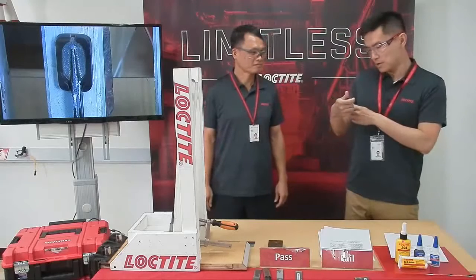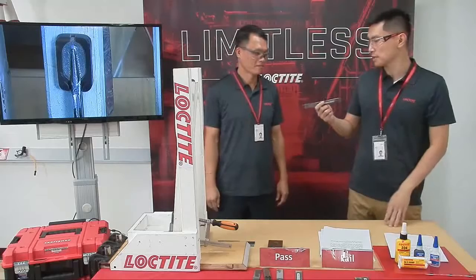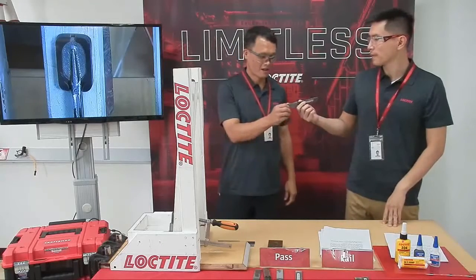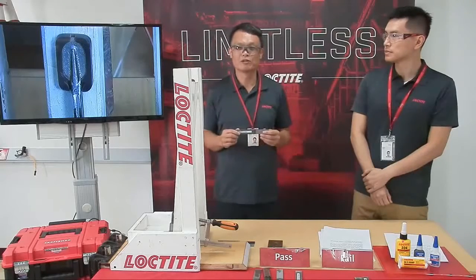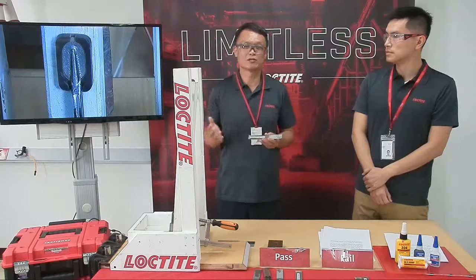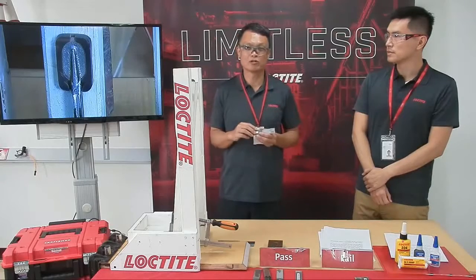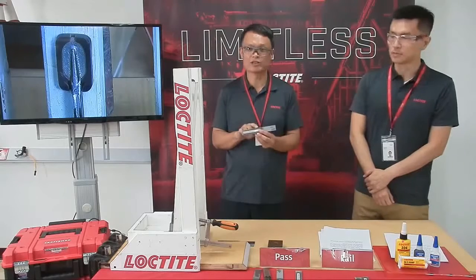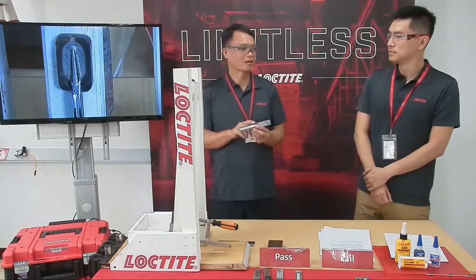So when you say structural acrylic, I know what acrylic is. Then what is the difference between these two? Because acrylic resin is very brittle, it's not the right candidate for structural bonding because it can't resist impact loading. We modify the formulation by adding some polyurethane resin into the backbone of the acrylic resin to make it more robust to resist dynamic or impact loading. Okay.